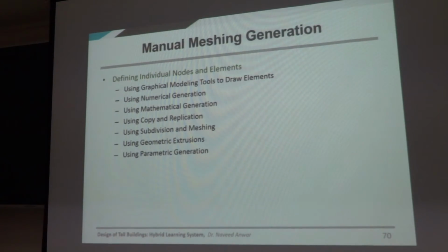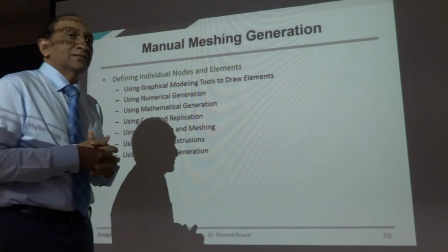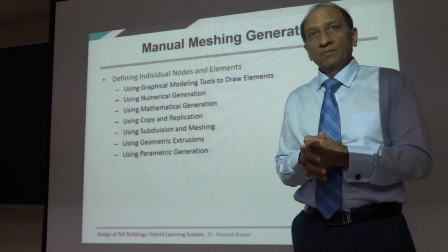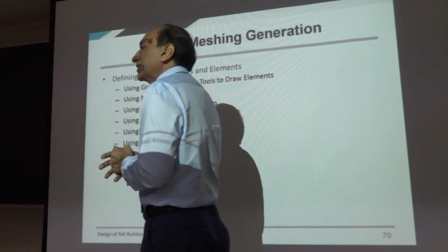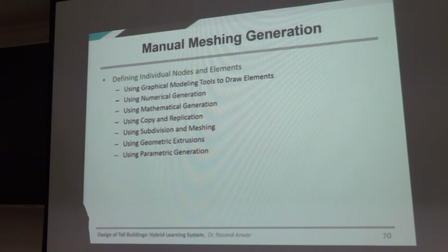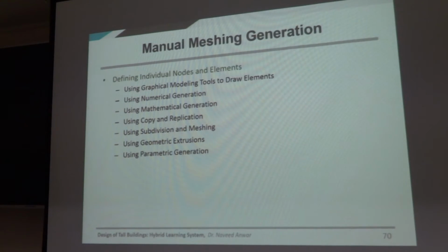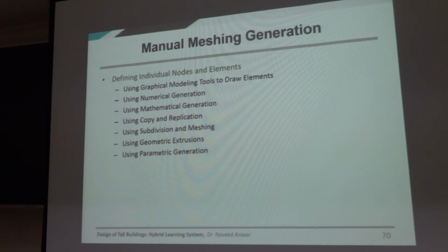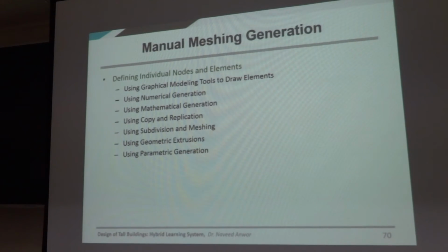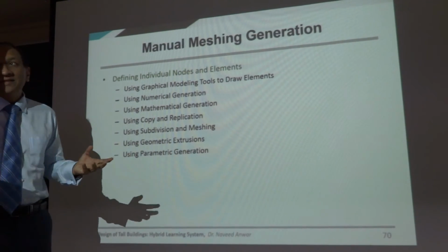First of all, the modeling of the slab for detailed finite element is quite, I shouldn't say difficult, but it's time consuming both for you and for computer, because you create a lot of mesh. You have many details, openings, inclined columns, staircases, cantilevers, shifting columns, many complications in a real slab. So if you want to do the detailed analysis in finite element, all of those things need to be modeled, and that creates just more work, but it can be done.